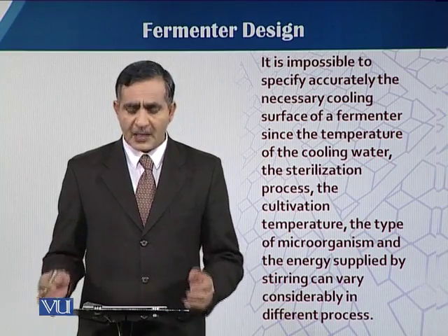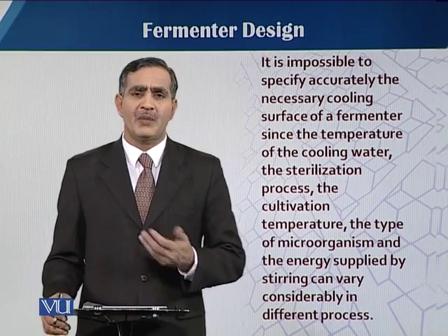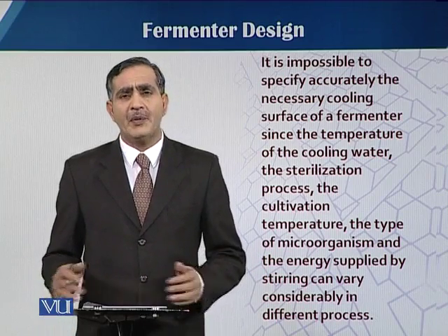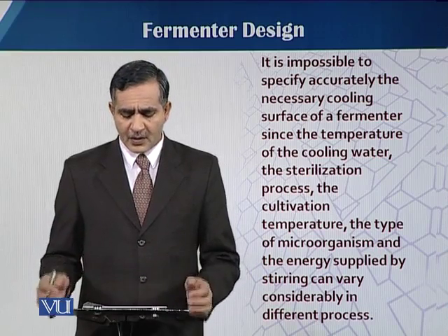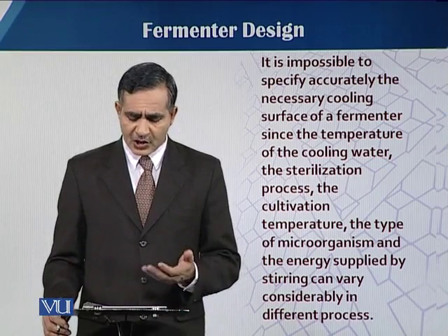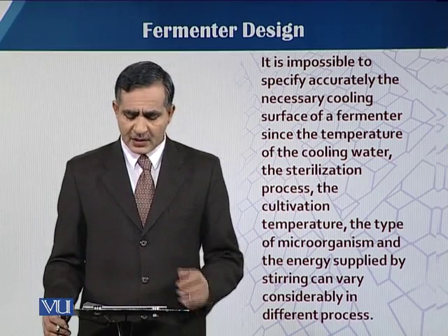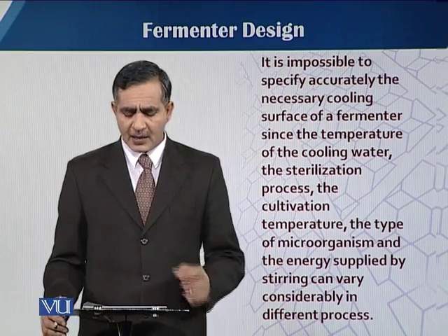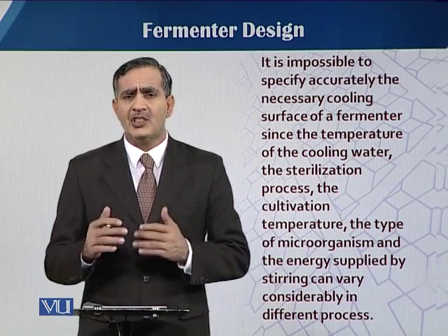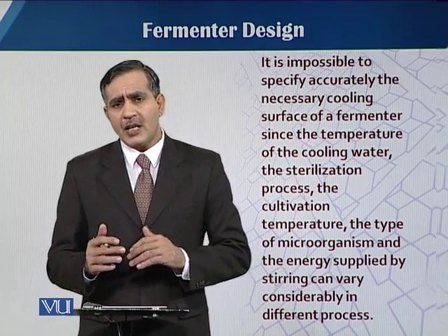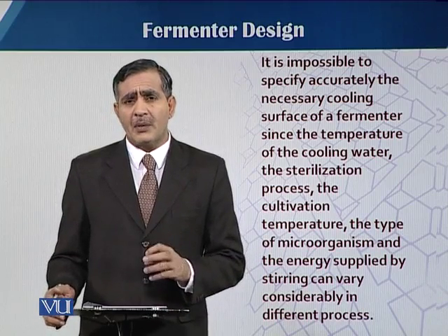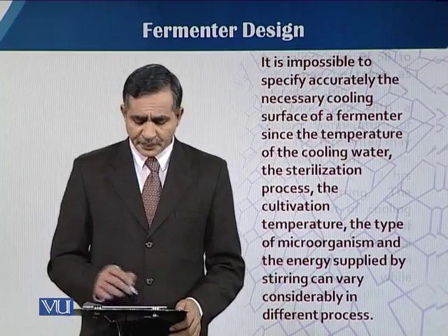That's why it is very difficult to calculate U. Sometimes we have to add to the surface of the fermenter, since the temperature of the cooling water, the sterilization process, the cultivation temperature, the type of microorganisms, and the energy supplied by stirring are different factors which change from time to time. So it is very difficult to determine by using this equation.